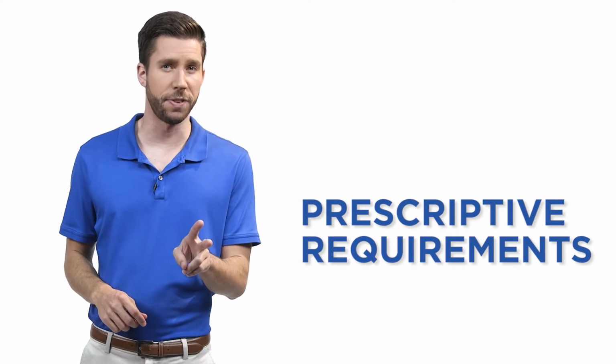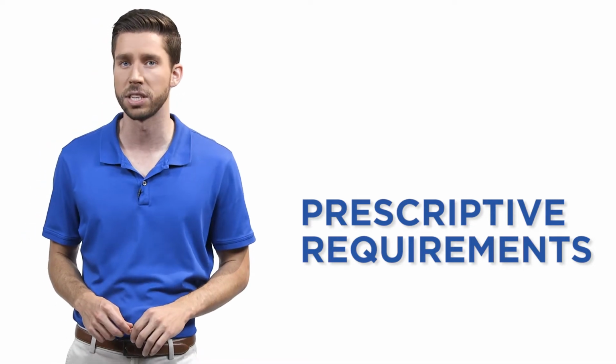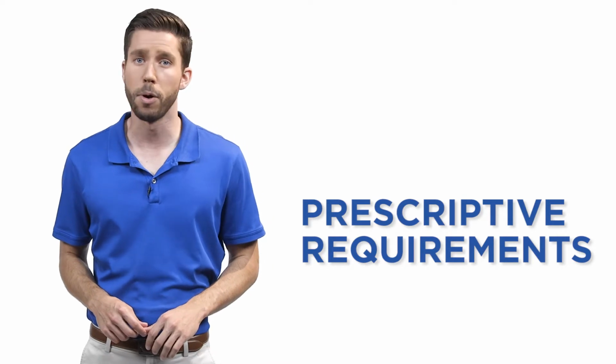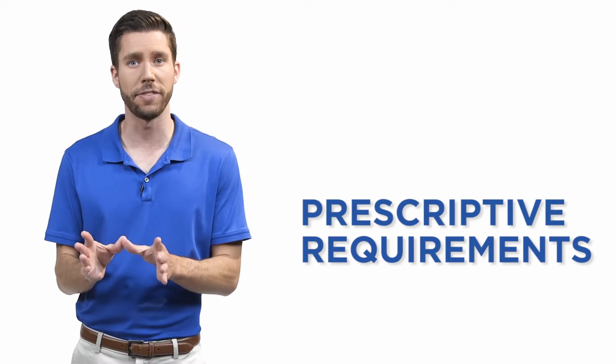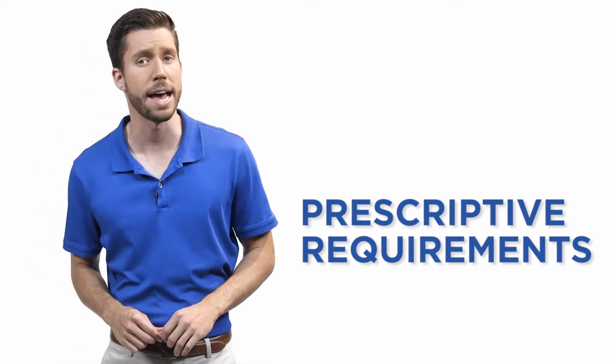In Module 2 of this video series, we learned about power adjustment factors, or PAFs, which are available under the prescriptive compliance approach. Multi-level controls are key to achieving some of the voluntary control strategies that qualify for PAFs. Institutionalized tuning and daylight dimming plus off are examples of this. Multi-level controls are necessary for these strategies. Without them, institutionalized tuning and daylight dimming plus off would not be feasible.